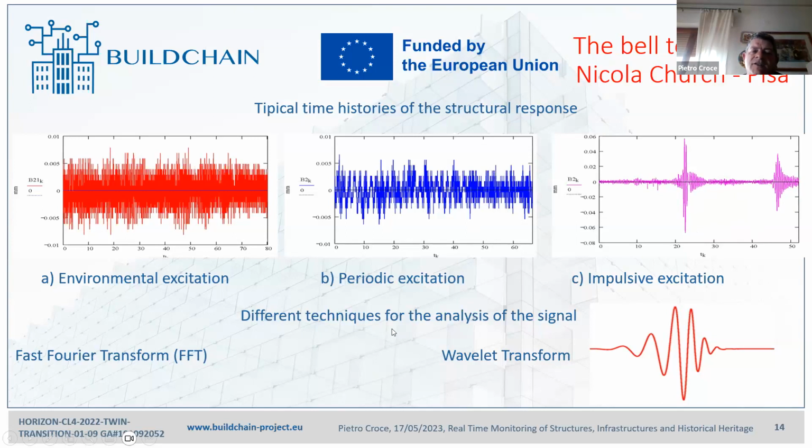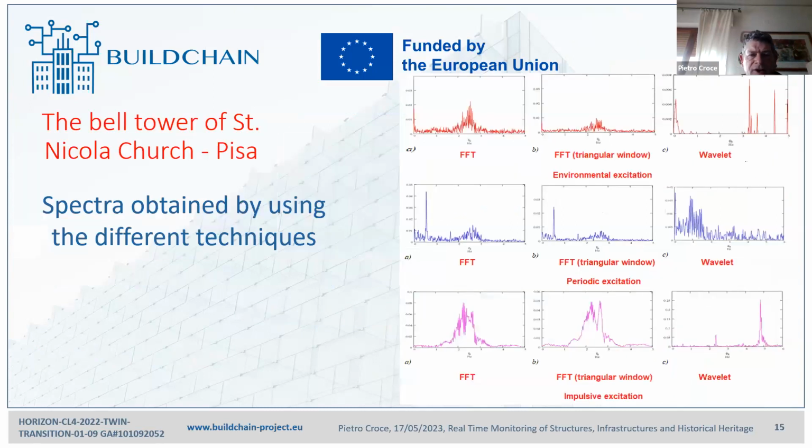And also for the analysis of the signal, we use different techniques. We use a fast Fourier transform, also with the windowing technique, as well as the wavelet transform, due to their different sensitivity and different ability to detect the frequency and consequently the modal shape.